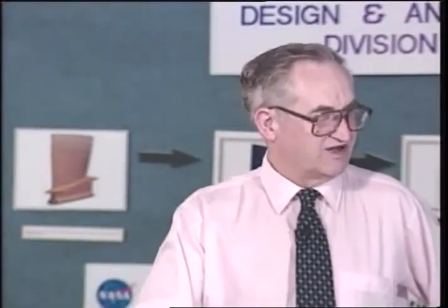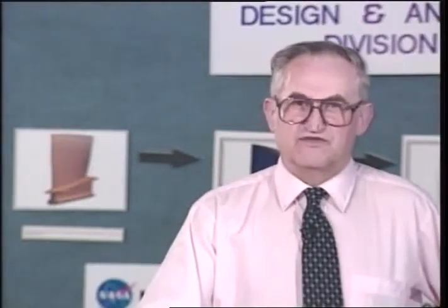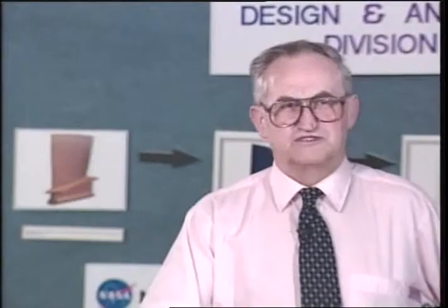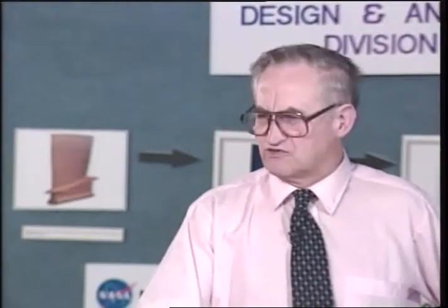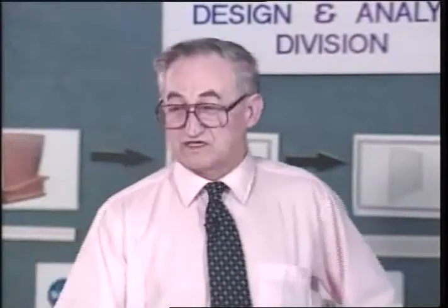It's done a lot, because with the chromate dye you usually use, the fastener is a gold type color, and you can't tell by looking at it whether it's zinc or cadmium. So the only way to find out is actually to run a test.